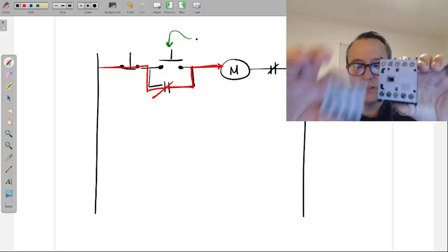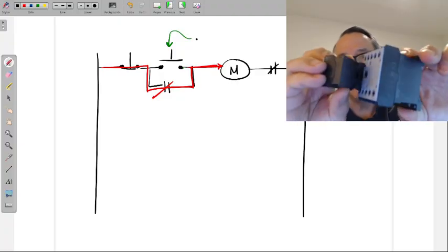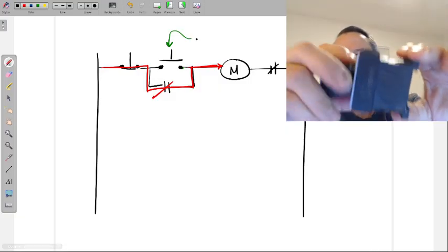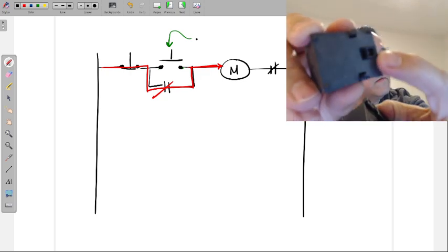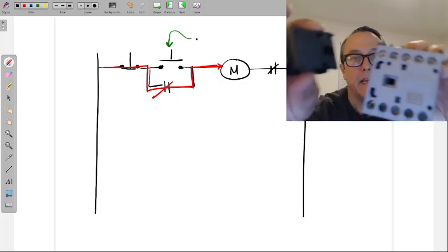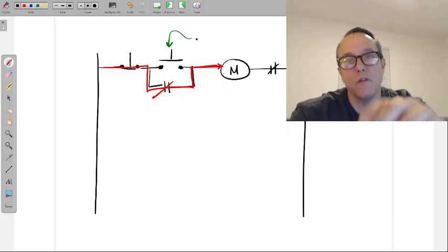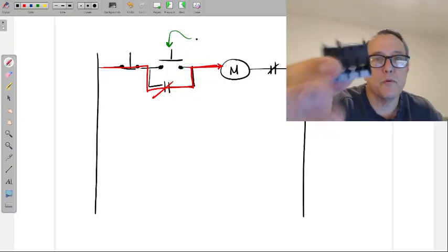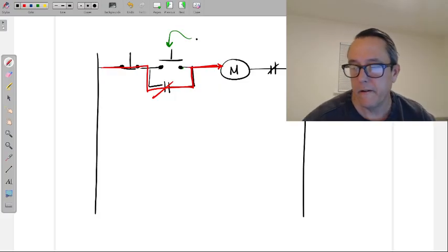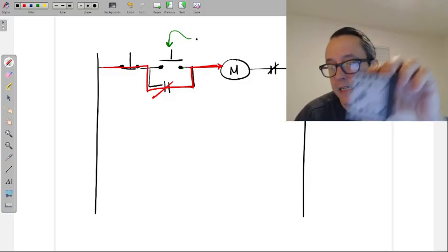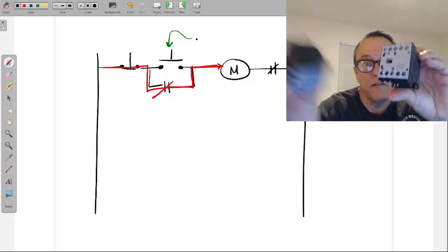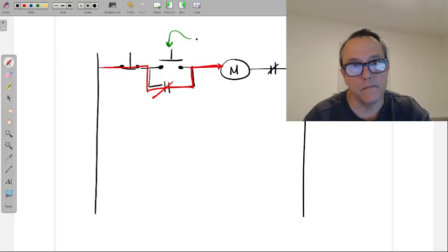All right, we actually do not like to use these. Also, they're mechanical, meaning they're attached to the back of this. So sometimes they do get stuck, or this little thing back here jumps, so that little thing right there, which is movable. It moves when this moves here. It'll jump or it'll miss that, and you won't get your auxiliaries engaged. Again, they just present a little bit too much of a problem sometimes when you have too many motor starters. So we don't use the auxiliary contacts, but these are for contacts, to open, to close. If you get rid of them, I got to replace them with something.